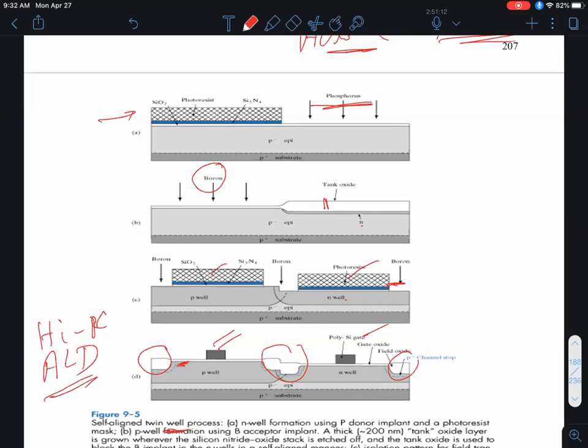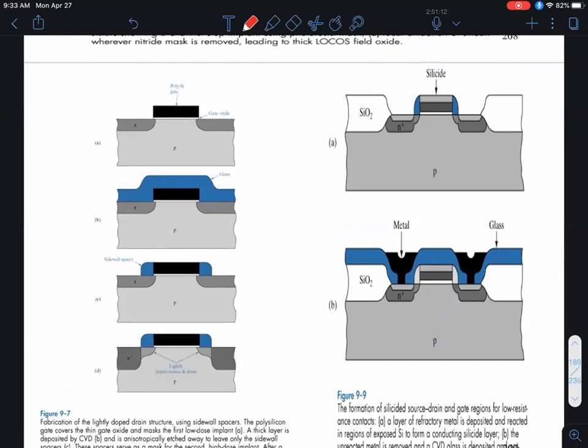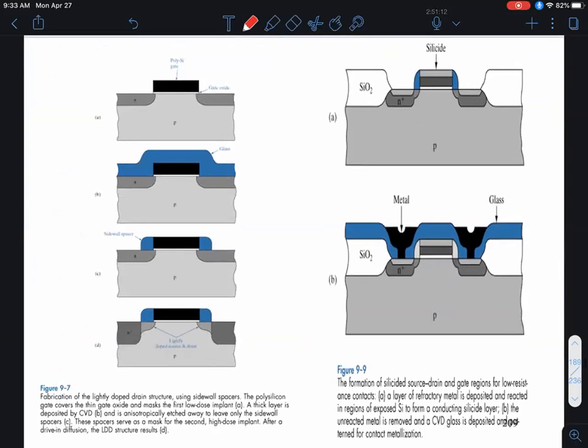After that, you then deposit the gate electrode. In the past, that would be made up of a highly doped polysilicon layer, where the highly doped polysilicon layer basically looked like a metal electrode. But these days, with high K, people actually now make metal electrodes that have to be patterned using photolithography and etched to form these electrodes with hopefully vertical sidewalls. The vertical sidewalls are very important, okay? The reason you have these vertical sidewalls is that it is then used to do a self-aligned implant of the source drains.